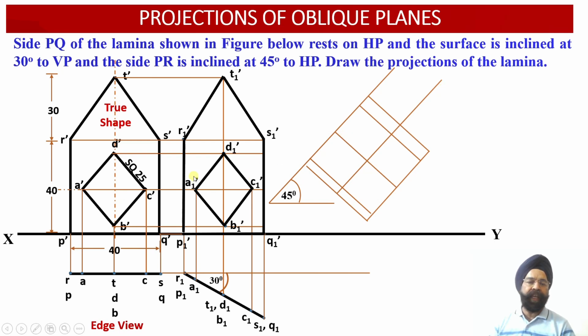Now we need to obtain inner points, that is A2 dash, B2 dash, C2 dash and D2 dash. Now we can check alongside this line, alongside this projector, we measure this distance. So B2 dash will be located. So one projection line we have drawn over here. So this distance is equal to this distance. So B2 dash can be located over here. Similarly, we have measured this distance as well. So once we measure this distance and draw this projection line, D2 dash point has also been located.